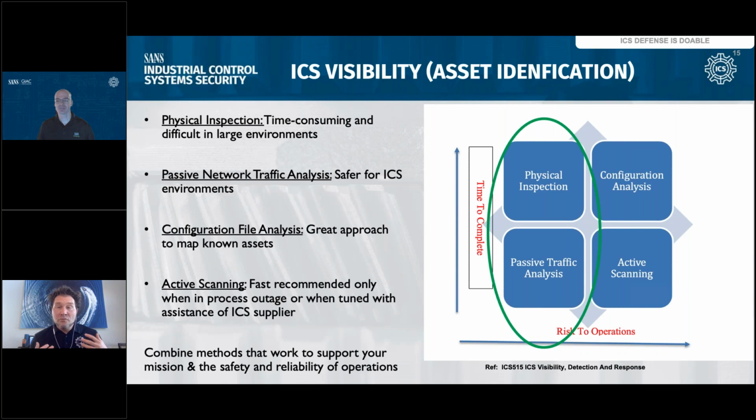Of course, there is physical inspection: getting to site, talking with the engineers, and literally with an encrypted laptop, with something as simple as a spreadsheet application, going around tracking what's in each rack, what PLCs are in the rack, what protection control devices are in the rack, what RTUs do I have out here. All of those things logged into a database is going to be critical for you to understand what your risk surface is when you get threat intelligence.